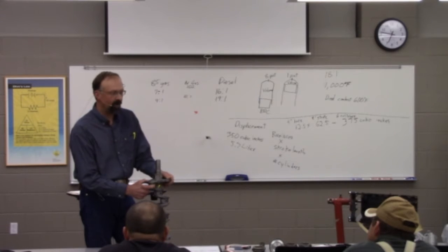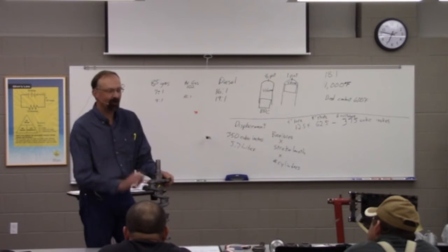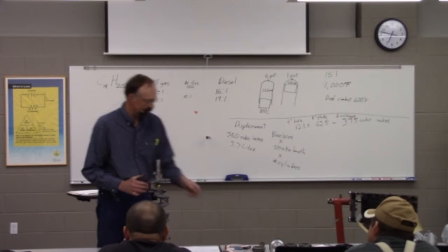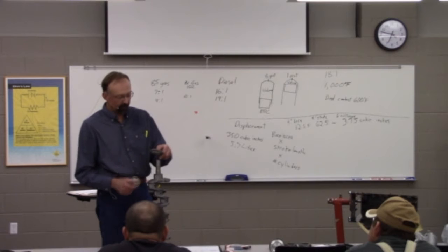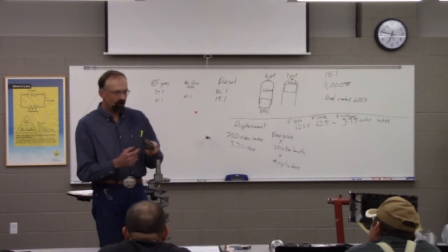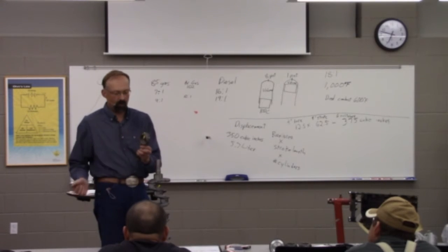You hear people talking about oil pressure. Well, the engineers have this pretty well figured out. They started out guessing and they've really fine-tuned it. But anyways, the clearance between this rod bearing and this crankshaft is going to be about 0.02 of an inch, and we need that full of oil. But of course, as we're using it, that oil is going to fall out the sides, right? So we need to keep pumping more in there.